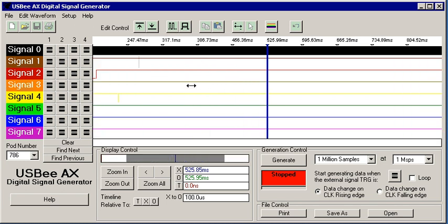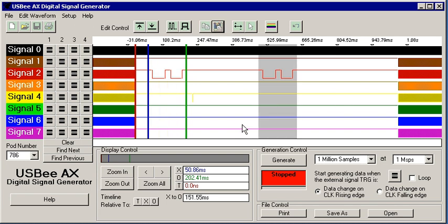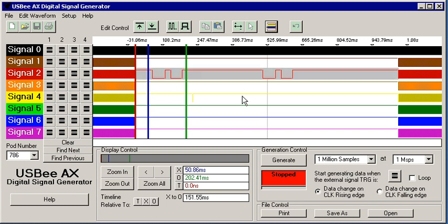You can also select particular portions of the wave. If this is a pattern that you want, you can copy, and you can place it by pasting at another position in the buffer. You can also choose an entire wave. Let's say we want to zero that whole wave out. You first select it, then press this, and then you can change it all to 0. If you don't like what you just did, you can press the undo button, and that replaces what you just did.